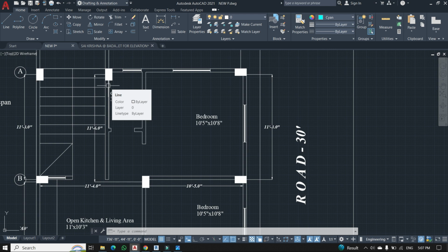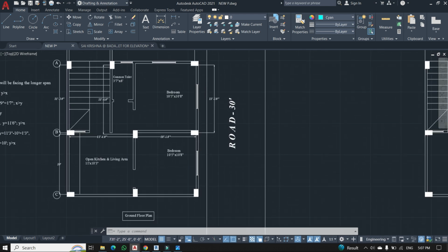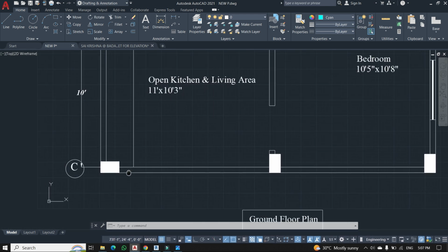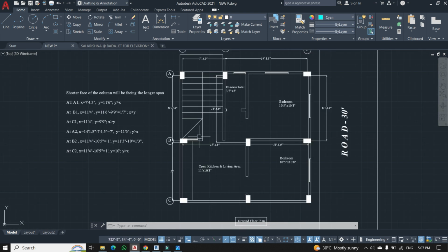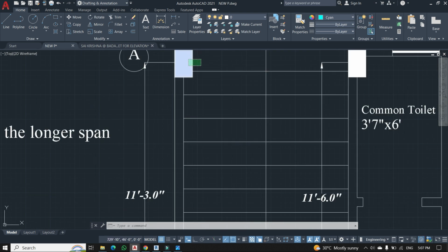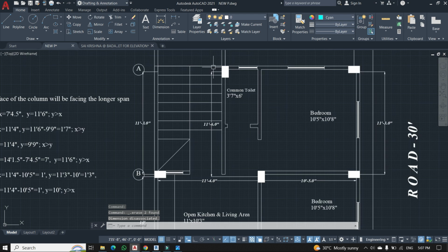So you need to go for site visits as well. Then only you will get a clearer idea. Okay. Now, wherever you are having the walls, place columns at those points. First thing, try placing the columns. I'll remove all these columns.